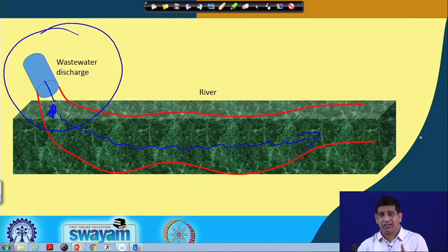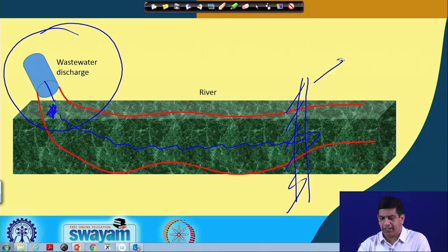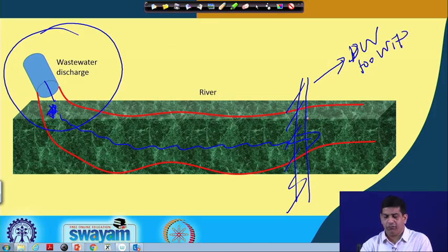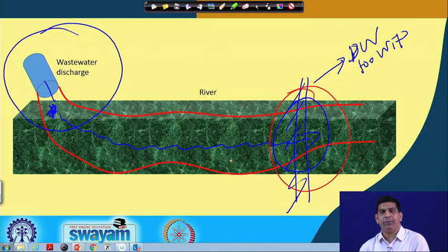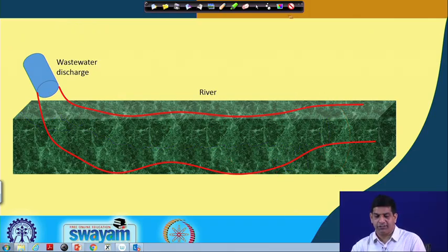Say I have a drinking water well over here, where I extract drinking water for my town water treatment plant. If the concentration at this point is much higher than what I can really treat, which does not meet the pre-treatment standard, I need to look at some other option for drinking water for a while, or try to treat it earlier, at a location before this if possible, so that we can still continue using it as a drinking water source.